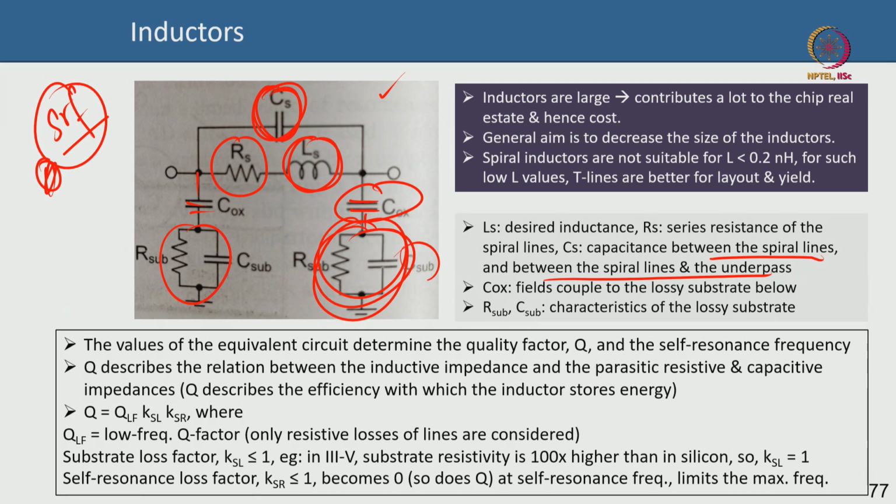Okay. Now Q factor is very important, as I discussed already in the last lecture, but I am just repeating because these are very critical as we talk about passives. These are important parameters that you have to really digest, understand and internalize. Q factor is the ratio of the desired quantity to the undesired quantity, simple. Different components will have different definitions of Q factor based on this. The fundamental definition is the same, which is desired divided by undesired, and so you want the Q factor to be as high as possible, you want the undesired quantity or the denominator to be as low as possible, okay, and the desired quantity to be as high as possible.